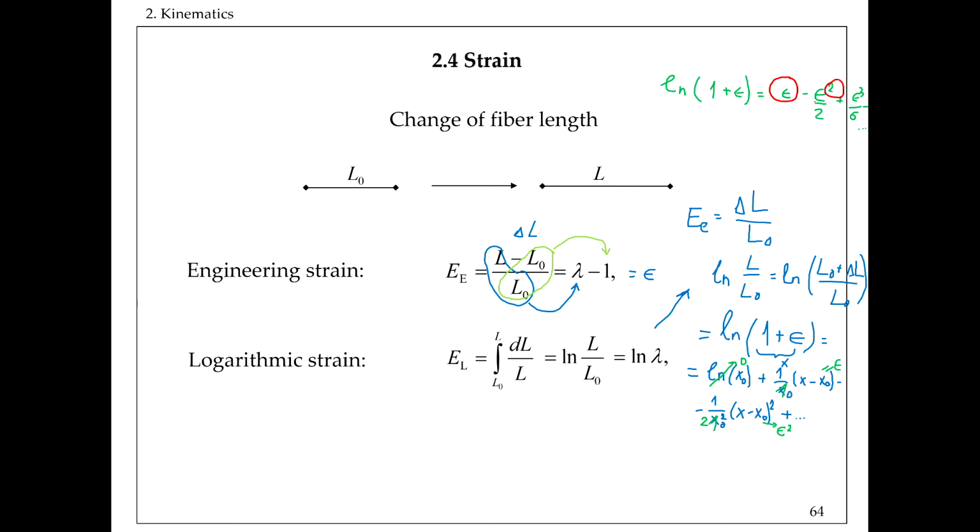So if the strain is relatively small, so if epsilon is a small number, or if a mathematician will write it something like that, right? Then we can neglect higher order terms. Then the difference between the logarithmic strain and engineering strain will be really very small. So we basically say that they would produce identical measures of deformation of strain.